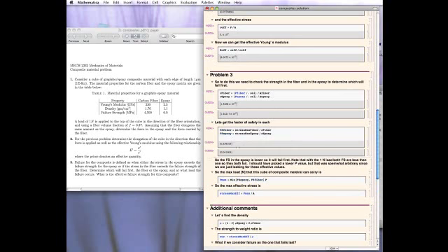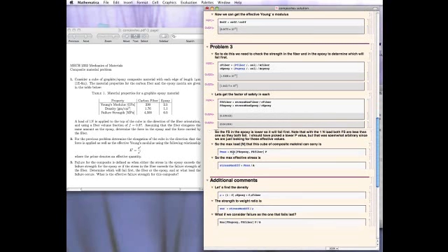They're all less than 1. So that means that they all fail. We get failure in the epoxy, and failure in the fiber. But what you can see here is that the failure in the epoxy will happen sooner. It has a lower factor of safety, even though the stress in it is lower than the stress in the fiber, but it has to do with the ratio, right? So failure will happen first in this one.